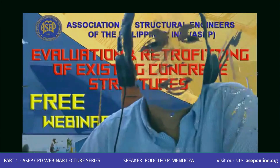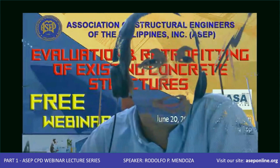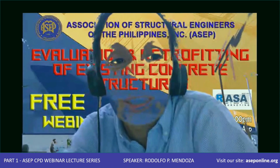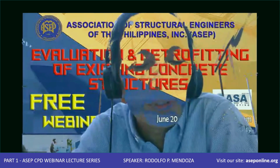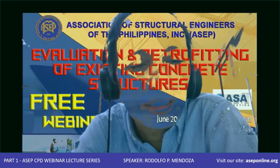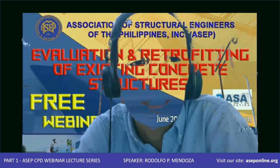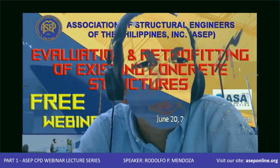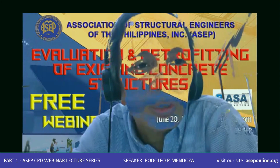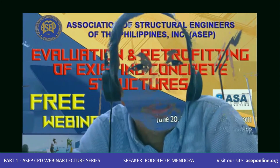Okay, related to that, Doc Mac, we have a question here. Based on ASCE 41-17 and ASCE 41-13, BSE-1N should be 2/3 of MCER, risk targeted. It is not explicitly stated that you cannot use DBE, the 475 return period.